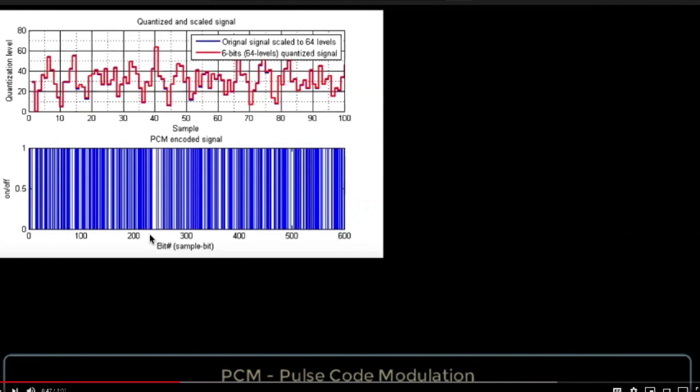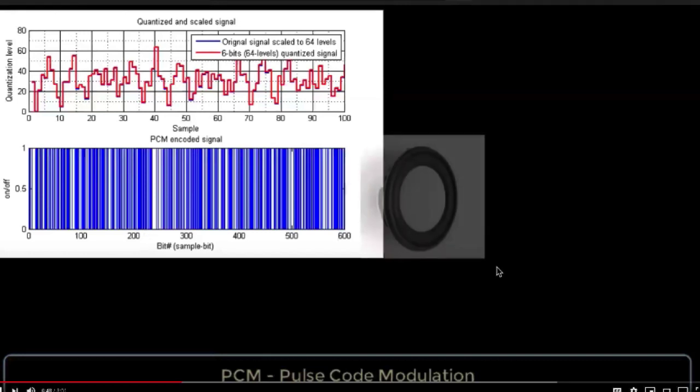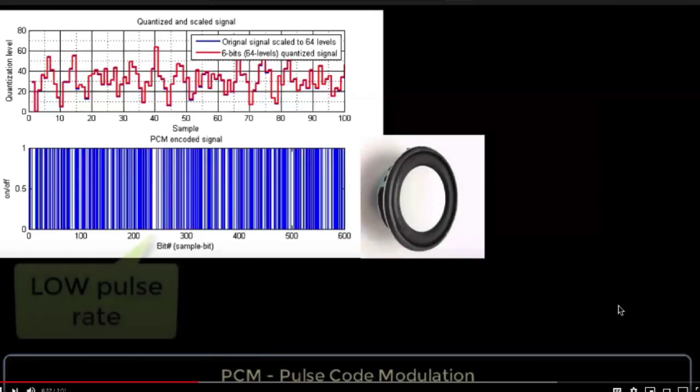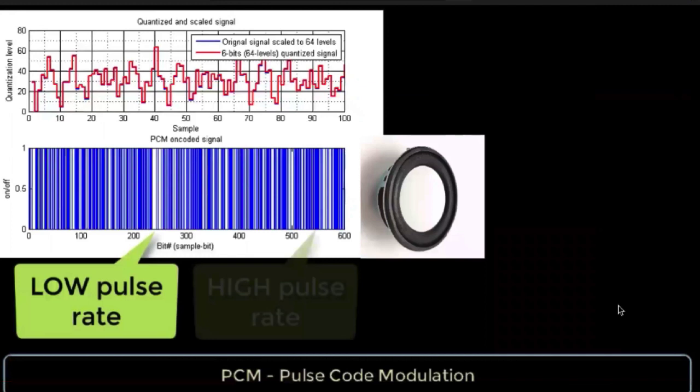However, using a digital pin, you can simulate the whole thing. You can just have 0 to positive. You can still have the cone of the speaker push out and come back, push out and come back. So it doesn't go backward, just push out and come back. If you write this fast enough, you will hear the low frequency and high frequency, just like programming. The answer is PCM, pulse code modulation. Arduino programs send digital pulses to the speaker pin.